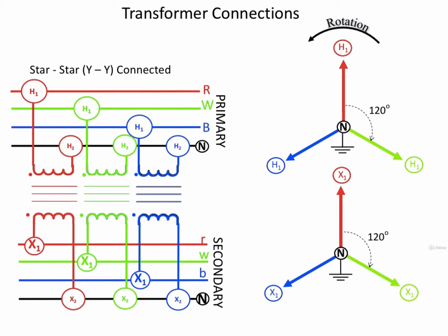Transformers for star connection and solidly grounded neutrals may be made with only one terminal brought out in a bushing and the winding insulation graded so that less insulation is required towards the grounding. This results in considerable savings in costs when constructing a transformer.